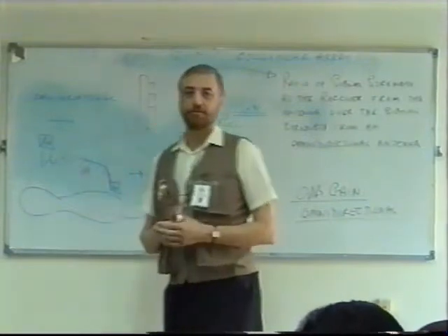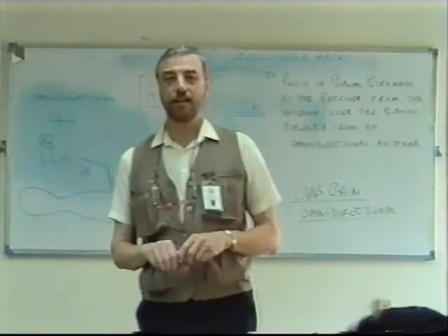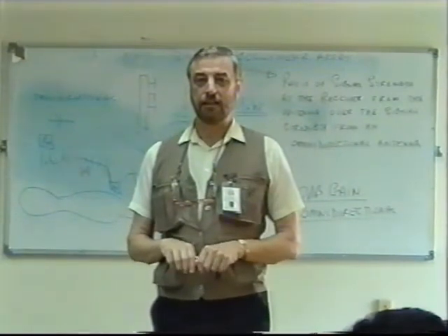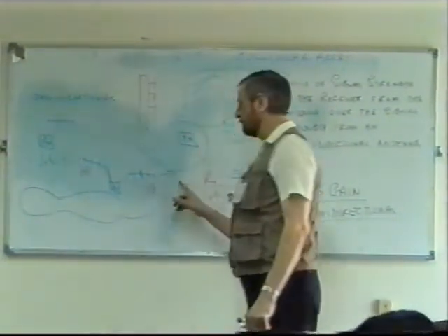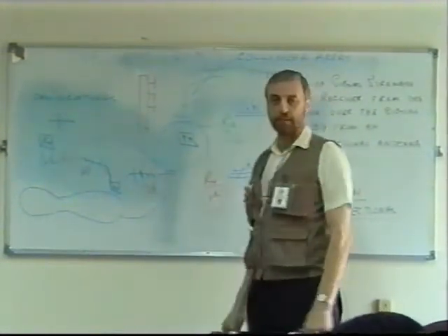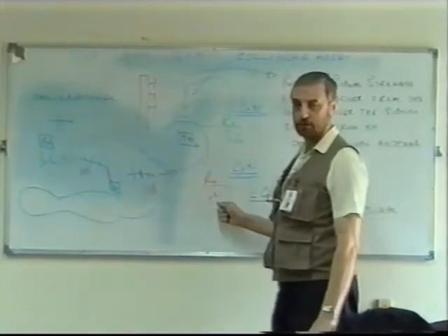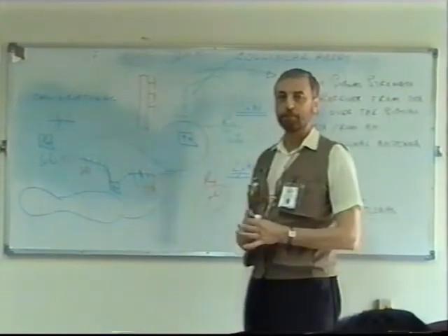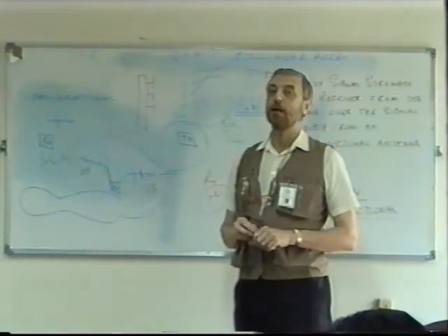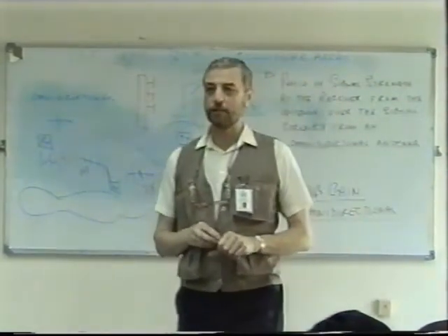So if you increase the antenna and the power and the dBs, the antenna needs to make it more sensitive to pick up the signal. Basically, yes, when you're talking about antenna, you're talking about antenna gain now. Think about your receiver power. How's any change here going to affect this? That's how you've got to think about it. The best RX antenna: if you go to the more dB, means more gain, so it's more sensitive to pick up that signal. That's right, yes. Sensitivity to pick up that signal.